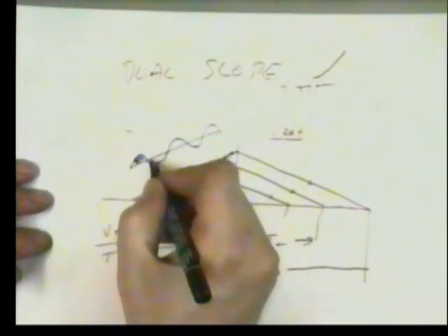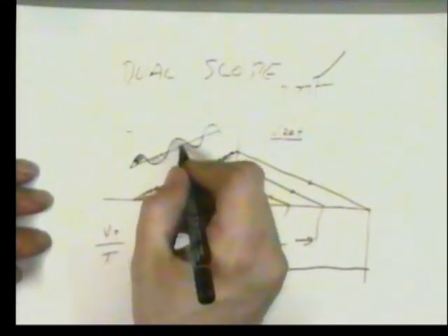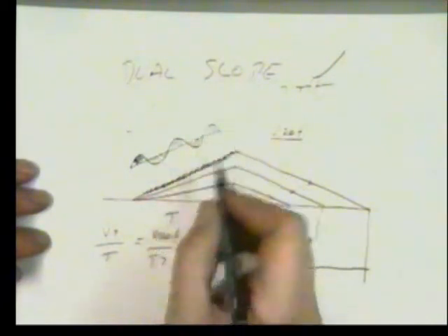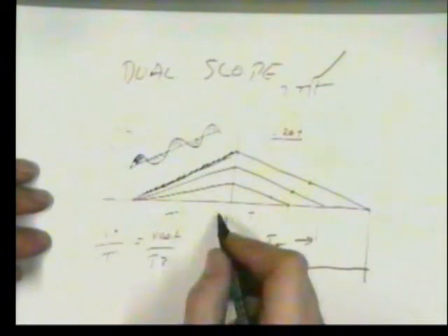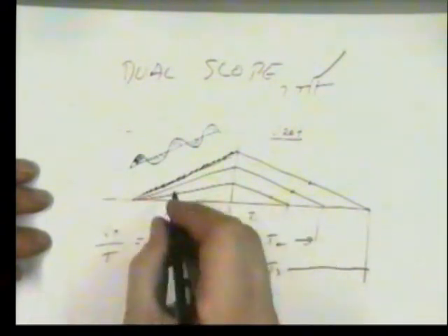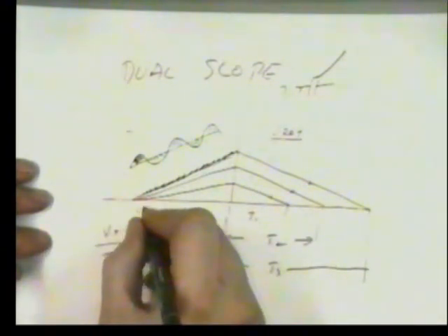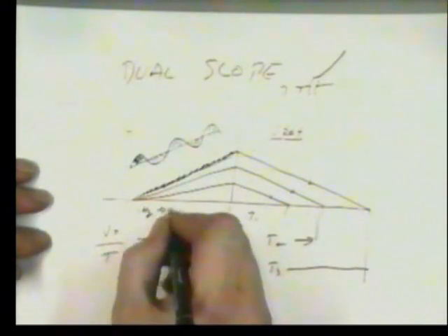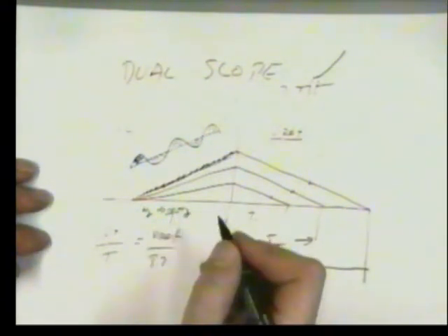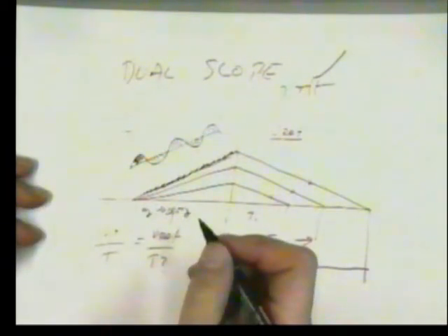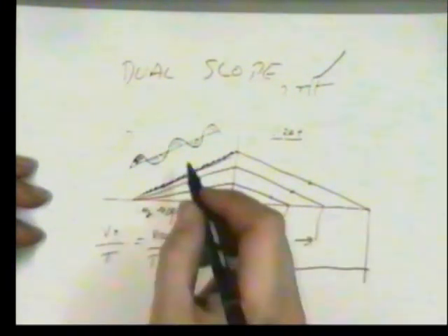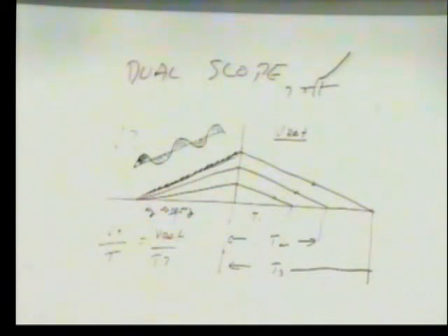The positive bits of noise will tend to cancel out the negative bits of noise. So overall, as long as you charge for a long period of time, you make that time quite long, and typically you would do that at 1 hertz to 10 hertz, so maybe 10 conversions a second, 30 at the most, but typically a few conversions a second, then the noise tends to get cancelled out.